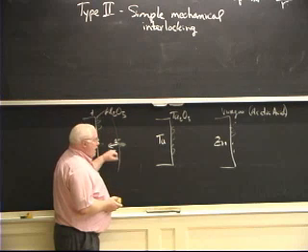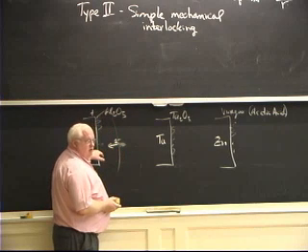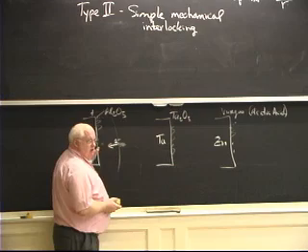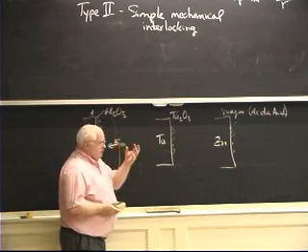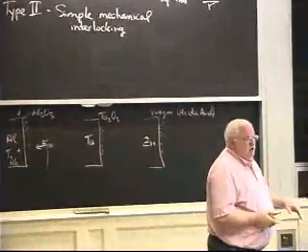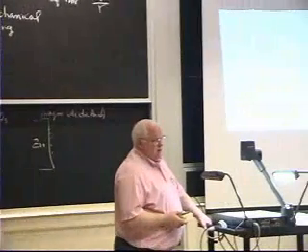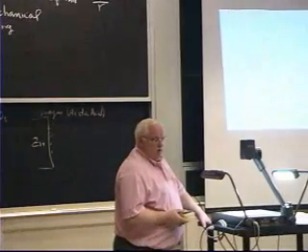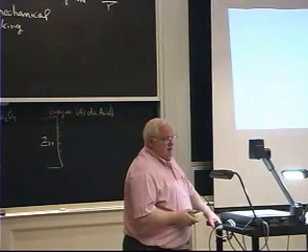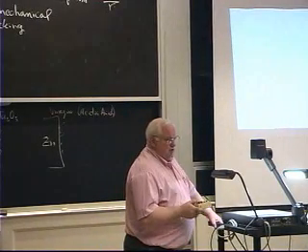If I want to grow it fast, I can use electrical energy, which will change the kinetics of this thing, and I can grow that oxide layer, but in a very porous form, and I can grow it to a fraction of a millimeter thick. Okay, it might be actually about 1/10 of a millimeter thick, about 4 thousandths, is as thick as it gets. Does that answer your question?